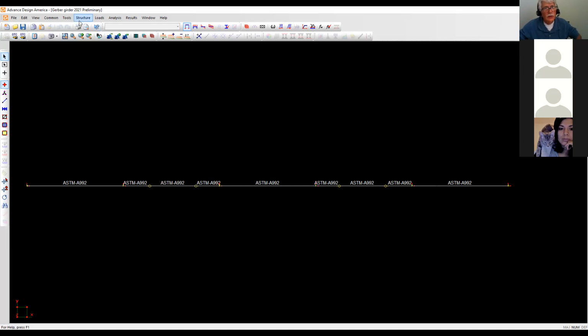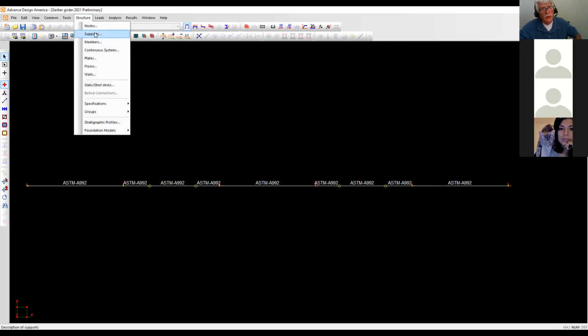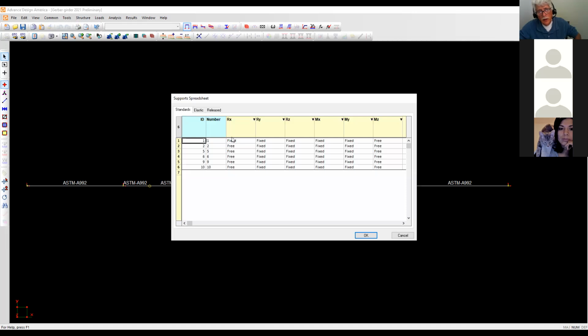And then after that, what you need to do is go and adjust. First thing I like to do is always model my supports so that I don't accidentally leave them as fixed, fixed, fixed. So once I've done my nodes, now I go to my supports, and this is where I change my support. Support number 1: fix, fix, free. Then support number 2. These I don't worry about. Like I said, this is only for three-dimensional analysis. I don't worry about these RZ, and all that. Then here I put free, fix, free.